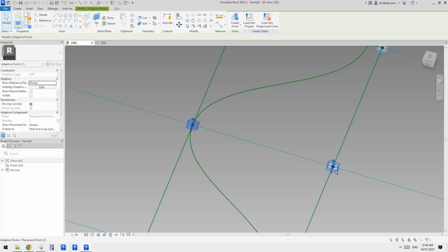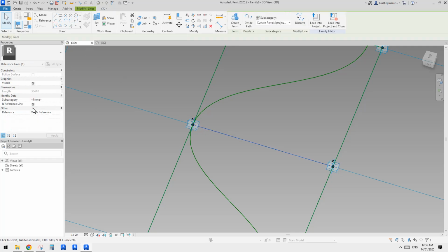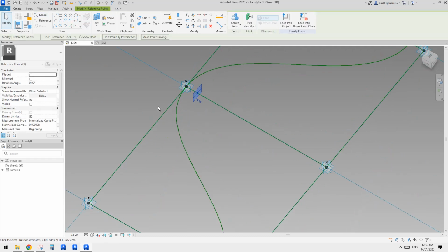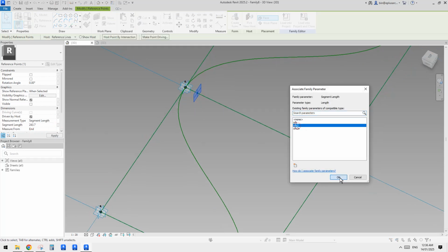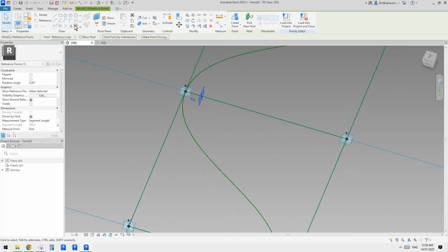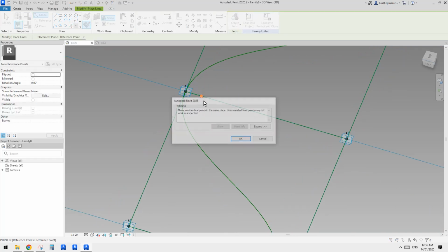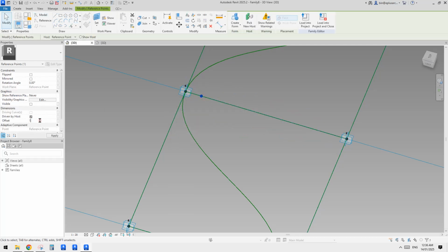It's safer to have a spline through points between points 2 and 5, and then place the point you draw on face onto this. So we flip this one and change to segment length, link to offset 2, and then we place another point, draw on world plane, set world plane, tab, and place onto that point. Select the point, give it 1.